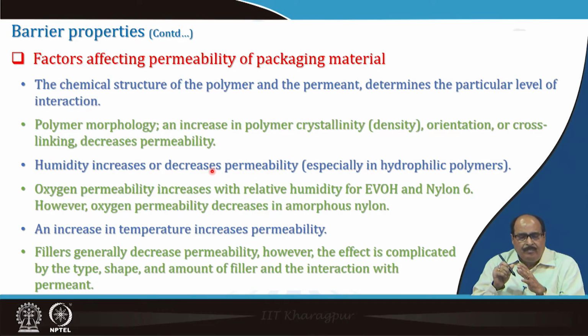So, there are various factors which influence the permeability of a packaging material, like the chemical structure of the polymer and the permeant, which determines the particular level of interaction. Polymer morphology: an increase in polymer crystallinity, that is density, or orientation or cross linking, decreases permeability.